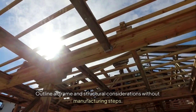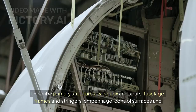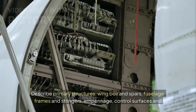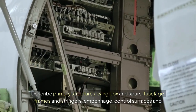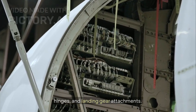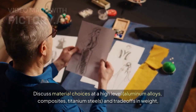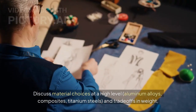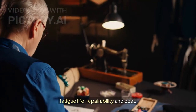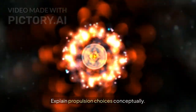Outline airframe and structural considerations without manufacturing steps. Describe primary structures: wing box and spars, fuselage frames and stringers, empennage, control surfaces and hinges, and landing gear attachments. Discuss material choices at a high level: aluminum alloys, composites, titanium, steels, and trade-offs in weight, fatigue life, repairability and cost.